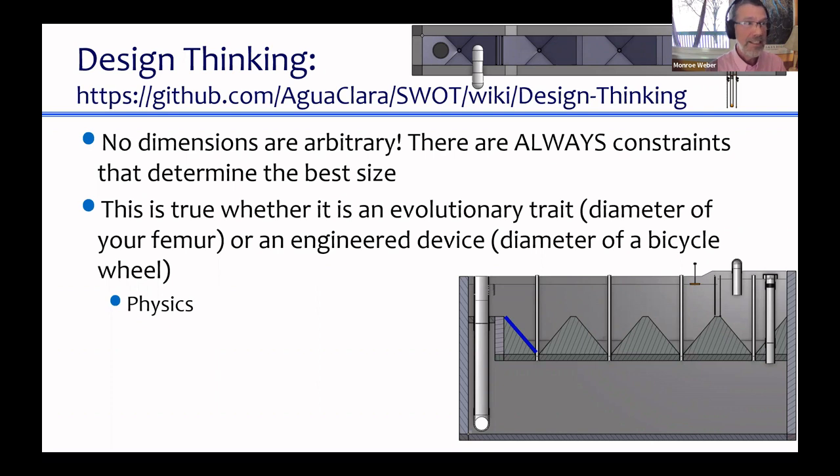All this gritty stuff, including small pieces of gravel that get brought in from your water source. And if you had a valve in the bottom of these tanks that you would open up and then close down again, eventually you would get some piece of gravel caught in that valve, and you wouldn't be able to get it closed, and the operator would get frustrated and crank even harder, and you'd have that valve broken. So the cheap solution is actually the easiest one to maintain.